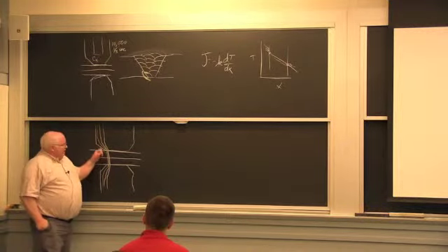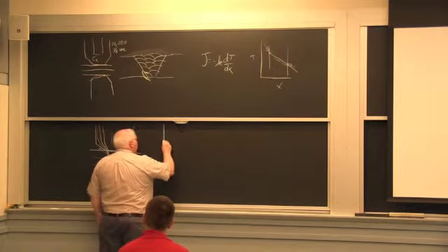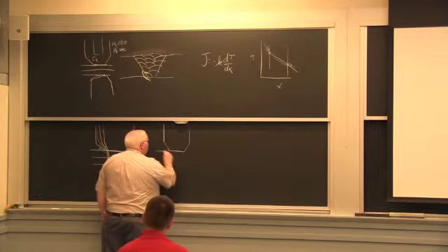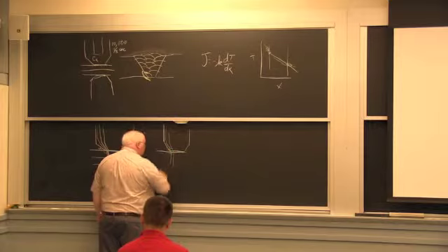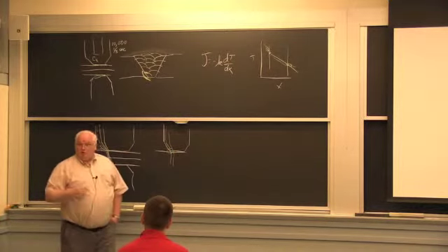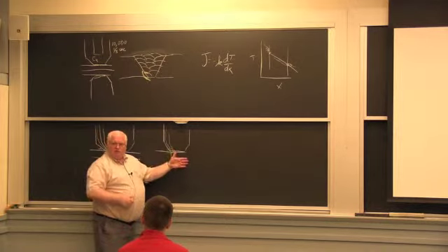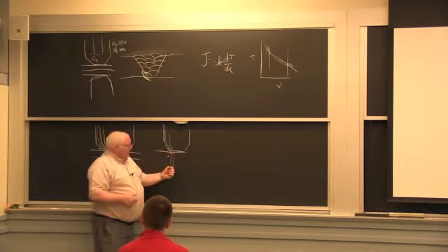And I said, that's the wrong angle. You should have a 45-degree angle on your electrode tips, because now the current doesn't bunch up as much. It's less of a stress concentration for the current. And we sectioned things halfway through. We did high-speed infrared movies, okay, of this stuff.